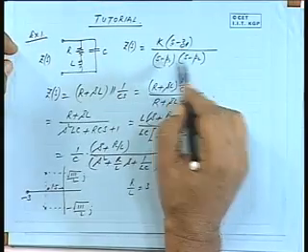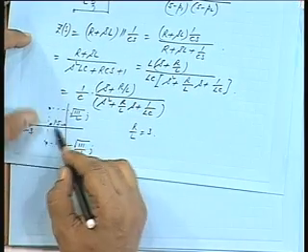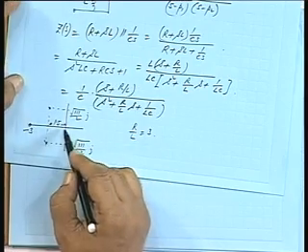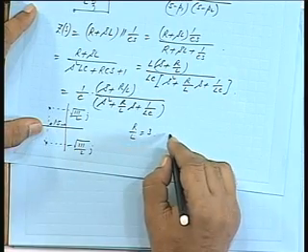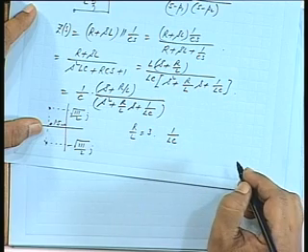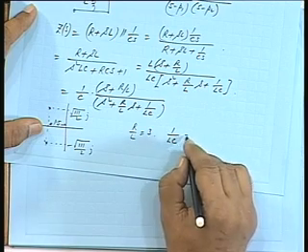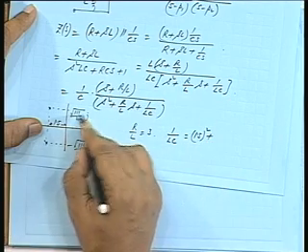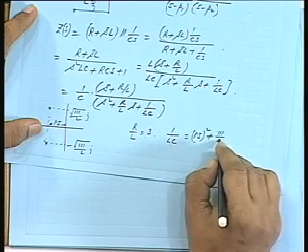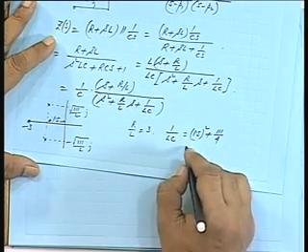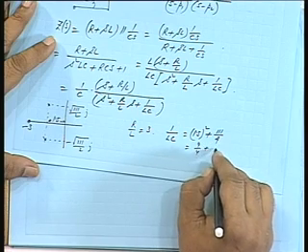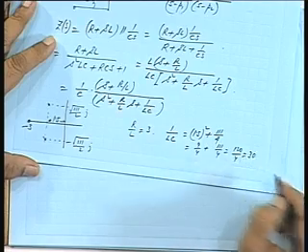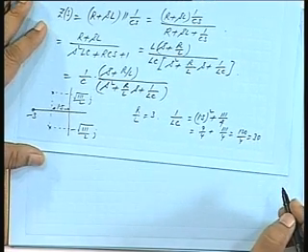See, it is product of P1 and P2. Here the roots are complex. So, it is minus alpha plus j beta, minus alpha minus j beta. So, what will be the product? Alpha square plus beta squared. So, 1.5 squared plus this squared, is it not? So, 1 by LC will be equal to 1.5 squared plus this squared, which is 111 by 4. So, this is 9 by 4 plus 111 by 4. So, that is 120 by 4, that is equal to 30.